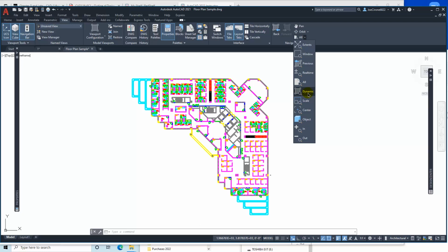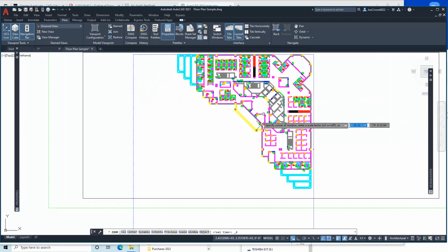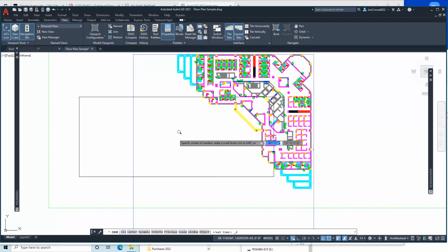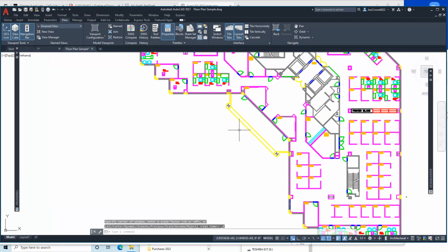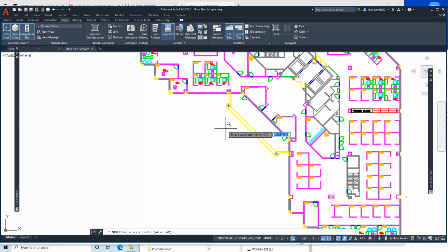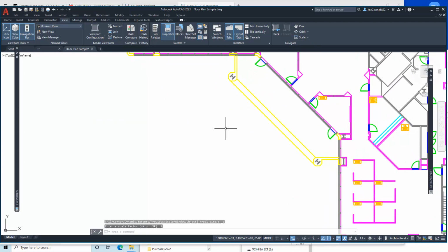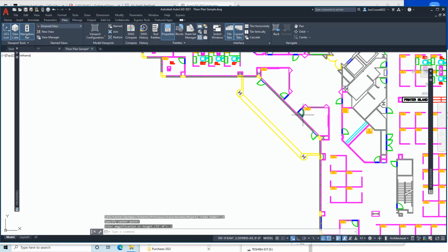A lot of these, as we start to look at them, they're like these older versions of CAD that would allow us to kind of shrink and modify, and then when we right click we hit enter and it'll zoom to that location. So it's not really a modern command. And zoom scale, we could zoom it to a scale factor of 1. Zoom center, we'll center it, I believe, on that location. Enter the magnification center, let's see, 1. And that's not really a useful command either.